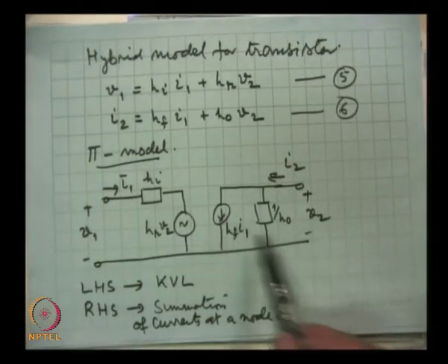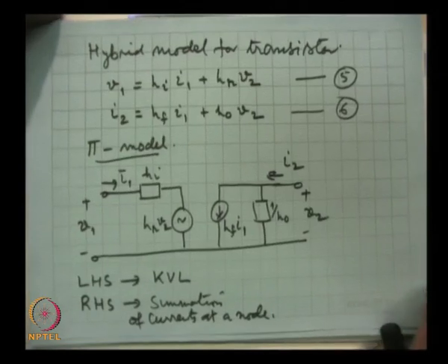So, we have arrived at the model, and this model is to be used for the analysis of small signal amplifiers. I hope you have followed the H parameters, their definitions, and then this model which we get on the basis of these two equations, and which can be used for the small signal amplifier analysis that we will continue in the next lecture.